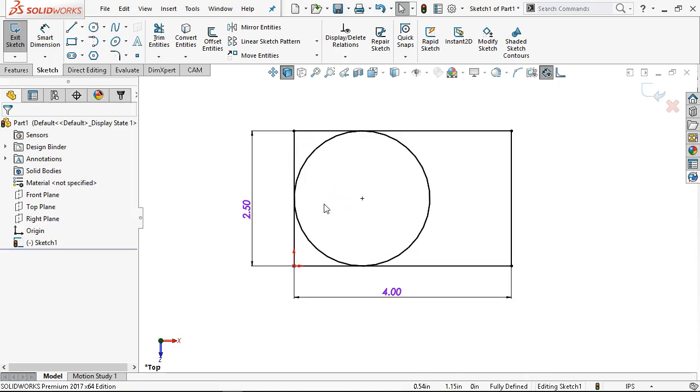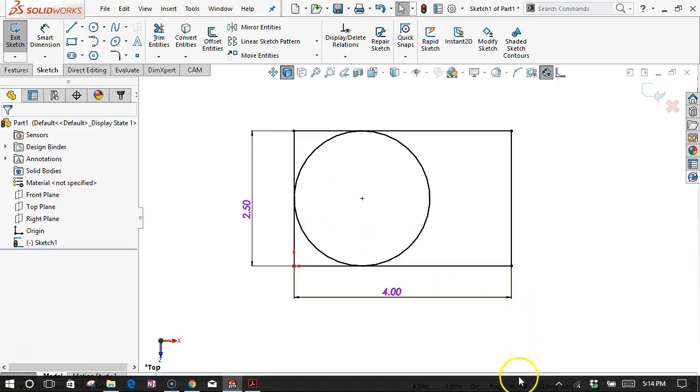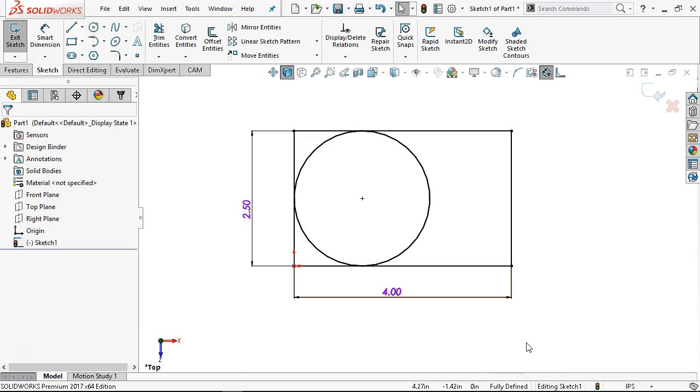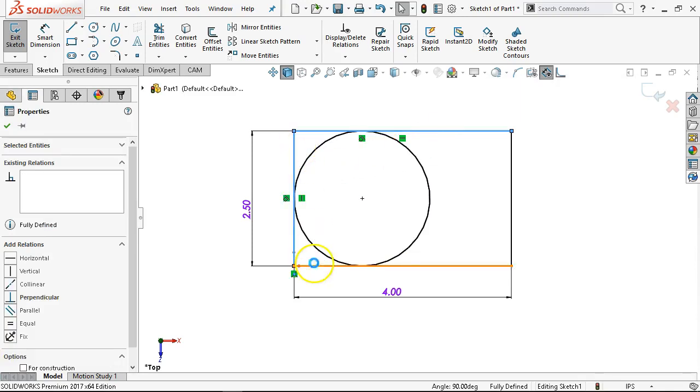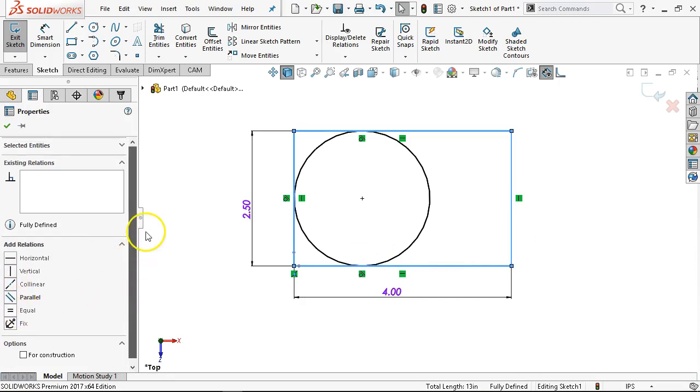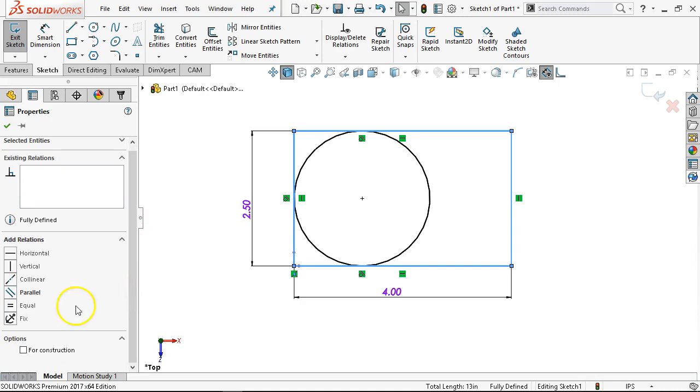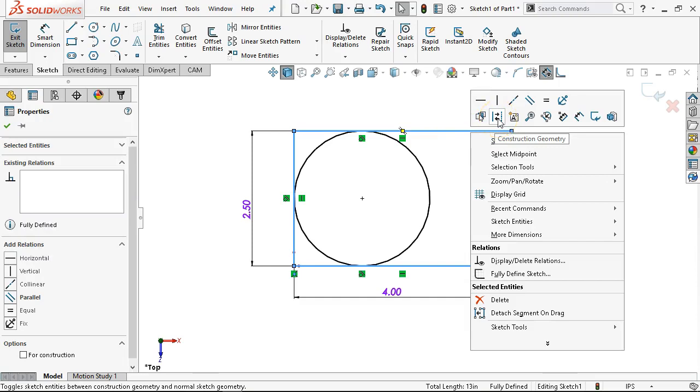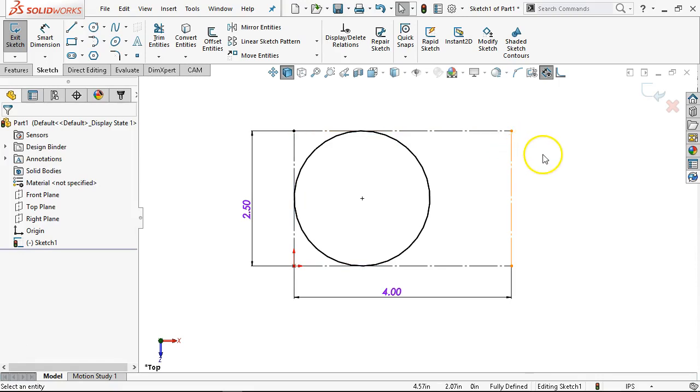So I'm right back in that same condition as 2 lines where, oh, showing fully defined. I'm not sure why it's showing fully defined, but I believe, well, we're already in contact. So let's do that conversion, and I'm going to select my object line so that I can verify. I'm going to switch over to for construction if I can see it. That's hiding underneath my timestamp. So I'm going to right click on the object, and the second row, second item is the little arrows. We'll switch that over to center lines or construction lines, however you like to call them.